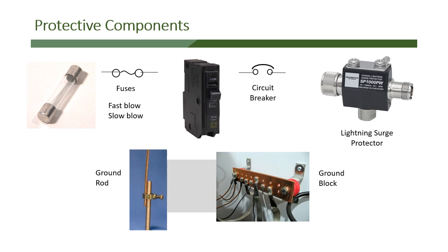A circuit breaker is basically sensing that temperature. It has two different metals that have two different expansion rates on them, and as this begins to heat up because it's going beyond its current carrying capability, the expansion triggers a spring, and it opens up the circuit. And so that's what's happening there.